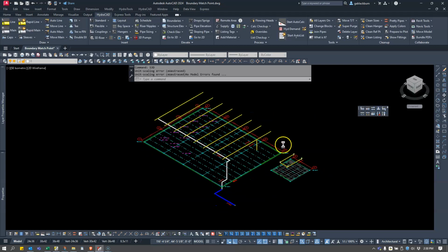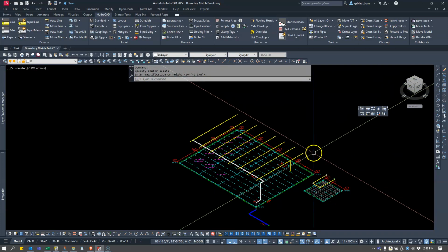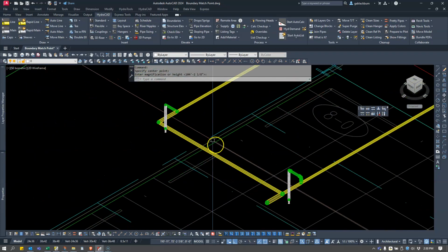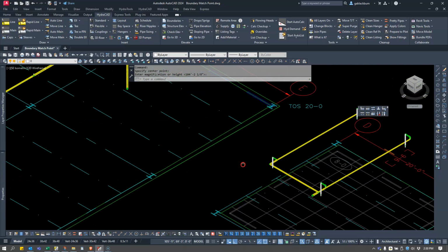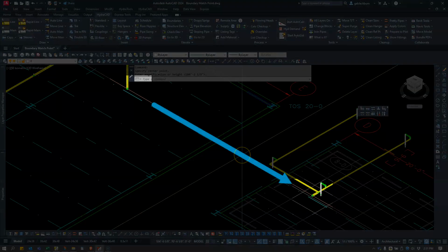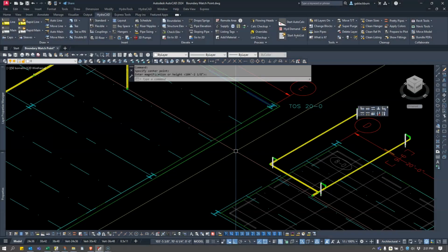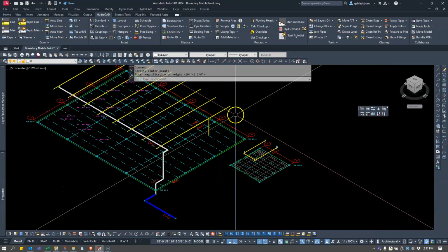And I'll click OK on this, and there we go. So we have the overhead sprinkler system. I'll call it our warehouse area, but then we have this little office over to the right hand side that we had to draw to the side. And you can see here we're connecting the two floors. If you notice my crosshairs where they're touching the low pipe versus the high pipe, you can see they do line up, but we just have to find a way to make sure that we can join them into one when we make our persistent model.